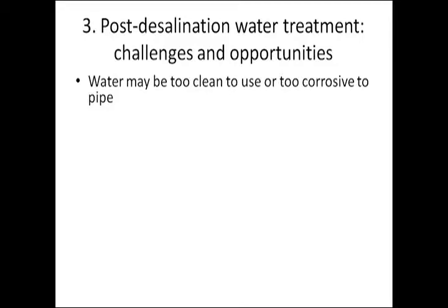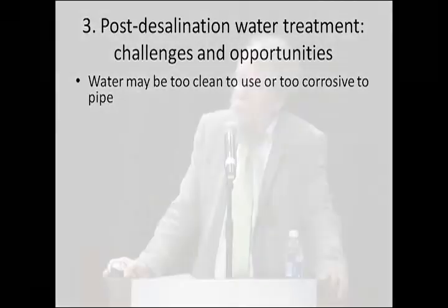It's a huge issue in the chip manufacturing business that low molecular weight organics do make it through membranes, and in that industry they need super high quality water, and if there are any low molecular weight organics in the water, they can really wreak havoc on their product. But for the most part, RO takes out almost everything.